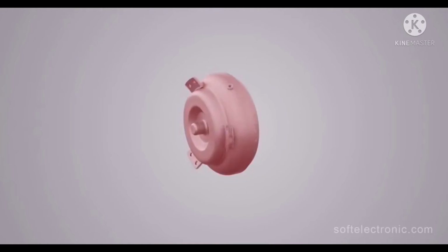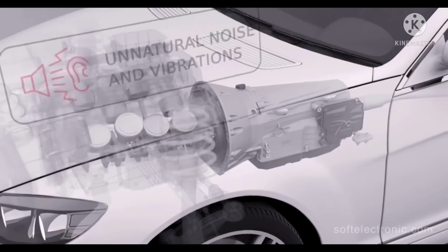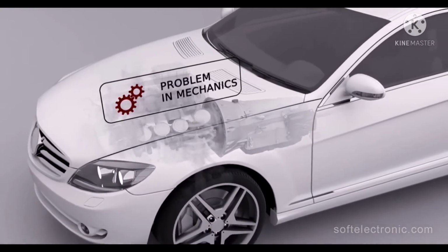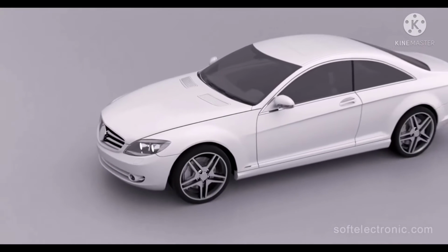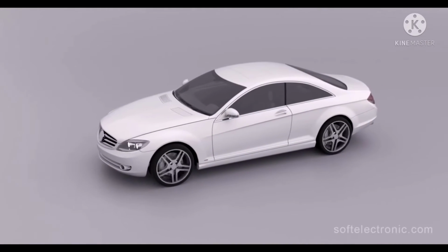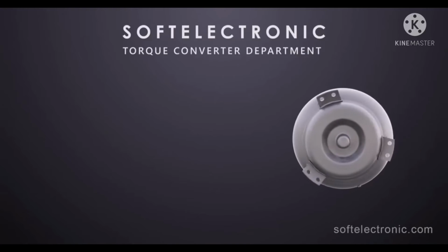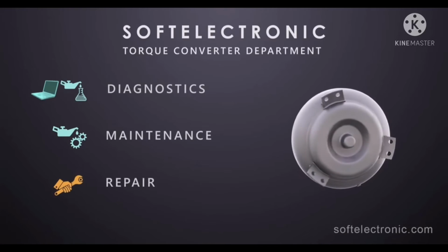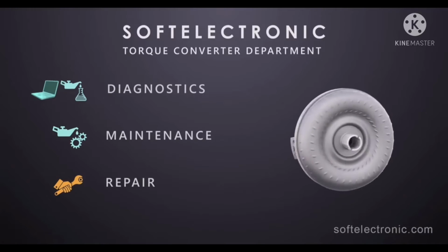The most common symptoms that may be a sign of a defect in the torque converter are the constant or periodic vibrations and noises that can be felt from the position of the gearbox. If the car starts off with difficulty, it may also be related to damaged mechanical components in the torque converter. In the specialized department of Soft Electronics, diagnostics, maintenance, and repair of many types of torque converters can be performed.